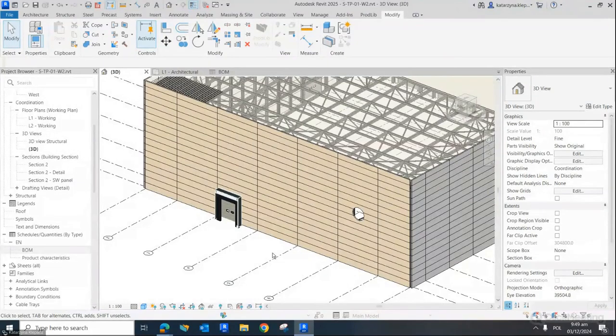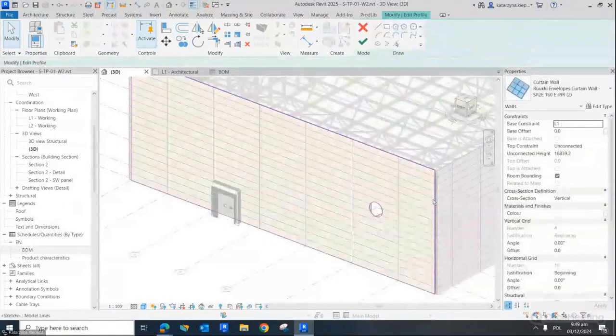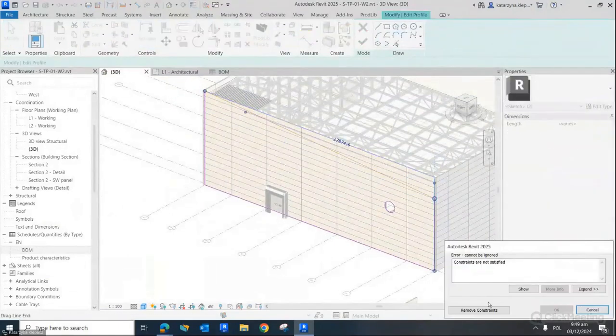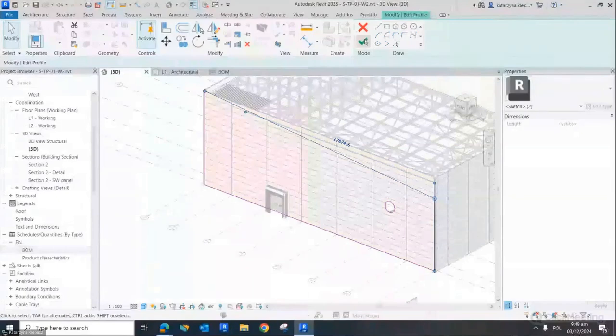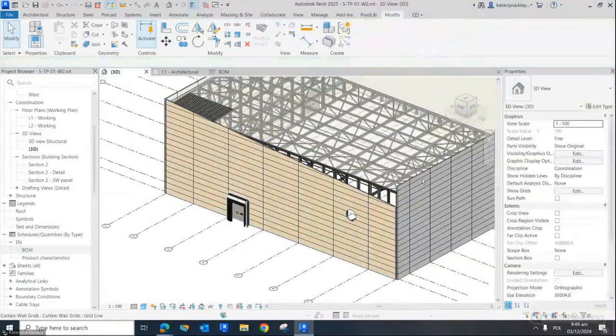Please check the library that we provide with a special emphasis on the curtain wall simple, since it's very easy to adjust. If there is some insertion point that you don't like, it's very easy to move it around. As you could see, it's also very flexible in creating openings. You can even change the shape of the whole wall if you'd like, just by creating a new outline.